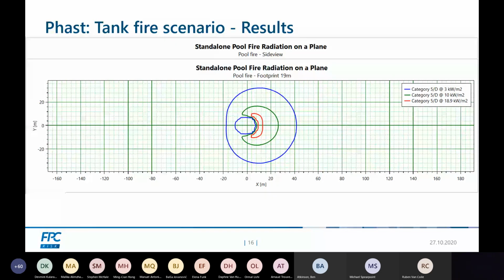And it shows us the horizontal reach of each contour at tank height. So this means that everything within the green contour at this height should be protected. This, of course, is very important for the calculation of your water demand and definition of your neighboring systems.